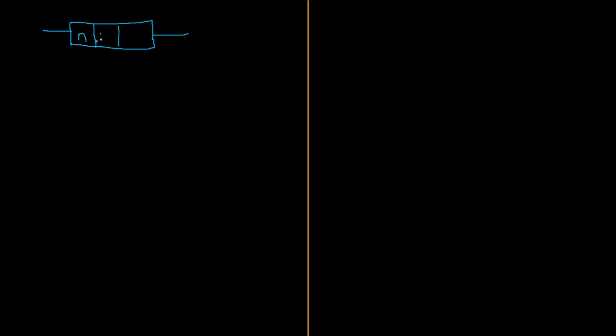Okay, so I told you we are discussing the NPN transistor. This P is basically two P's inside, just to remember. I am calling this the collector junction and this the emitter junction, because it is connected with the emitter. This is connected with the collector, and in the center point we have the base B. Now when the collector junction and the emitter junction are both in forward bias, then the region of operation is simply called the saturation region. That is the first conclusion. Now let us make the second conclusion.